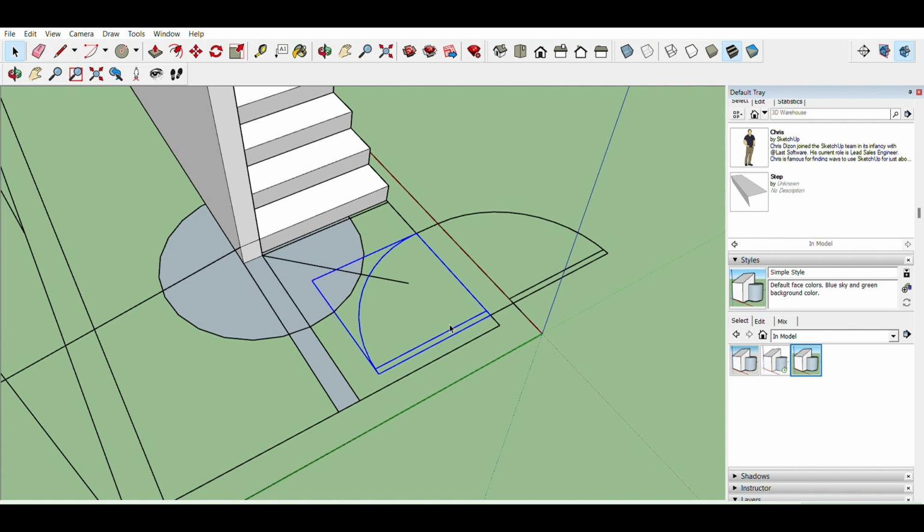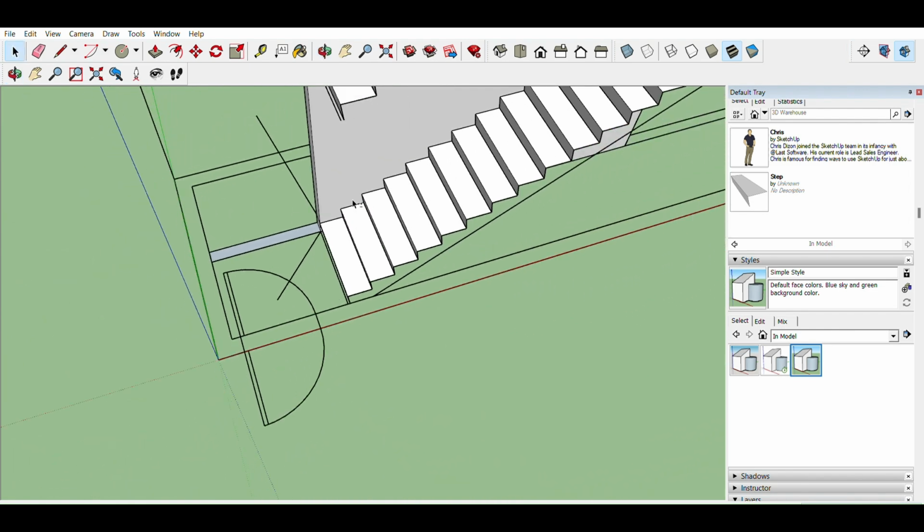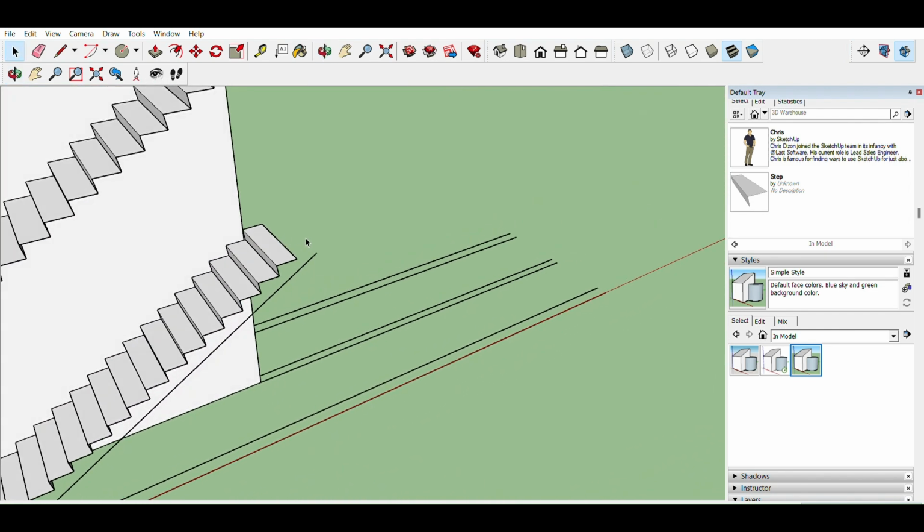The bottom one swings to the exterior, but all the other ones swing into the stairwell, so that this 2'6" dimension is fairly critical. So now we have that laid out. So what we're looking at is 4'8" from the nosing. So from the nosing, 4'8" back.